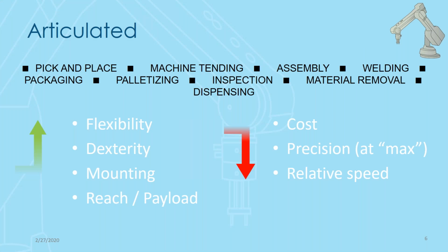The articulated robot, that's when most people hear the word robot, that's typically what folks are thinking of. The big automotive assembly line with many robots going to town, welding on frames, et cetera. And so that's the real typical robot. They would be referred to by their degrees of freedom. So typically, a fixed axis articulated robot arm is pretty typical. It means there's 6 axes of rotation for all the different joints.